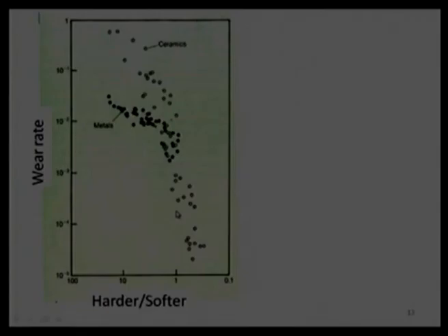It is nothing like I keep 60 HRC hardness of one surface and 60 HRC of hardness of other surface, and I try to slide one surface on the other surface, there will not be wear. Surely there will be wear. Even though there is an equal hardness, there will be some wear. Asperities, however, can be treated as a cantilever, and their height is different.